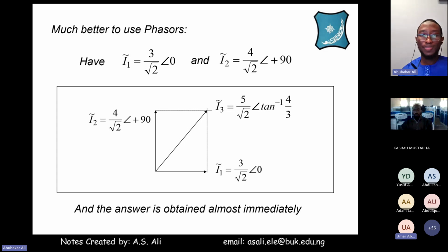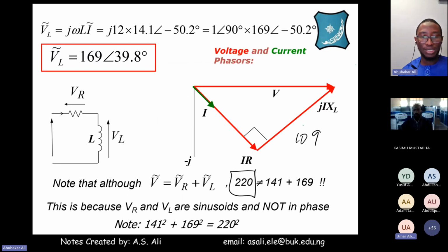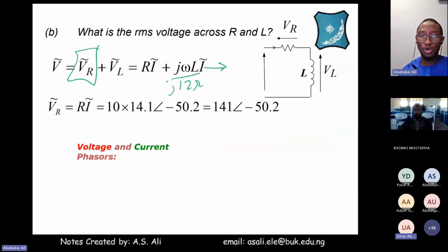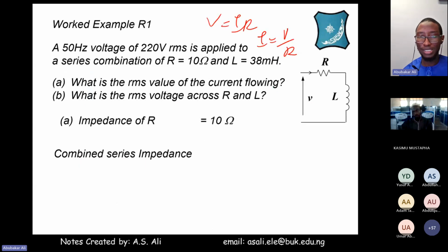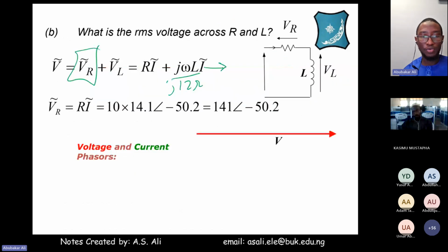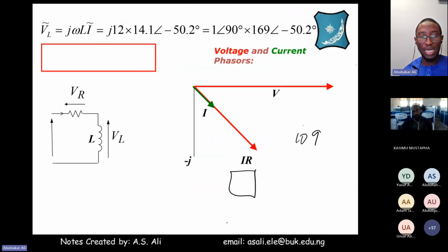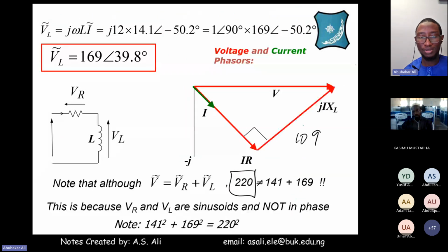We were supposed to cover this part last week. But the main key takeaway from here is you understand how to work with phasors, which I am happy about. Some of you are able to do the conversion directly and instantly from Cartesian to polar. And you know how you can come up with the Argand diagram. Not only that, you know how you can take advantage of these complex numbers to do AC circuit analysis, which we just did an example of. And the last example we just did was to show you how efficient using phasors is when you are trying to do computations. Okay?